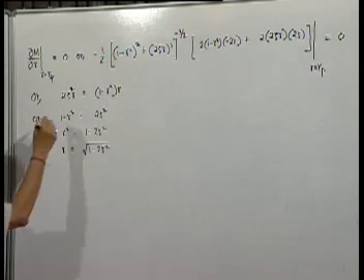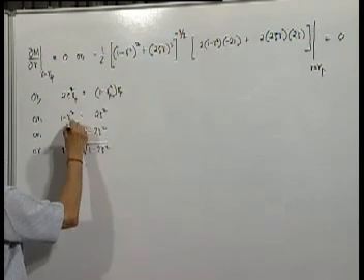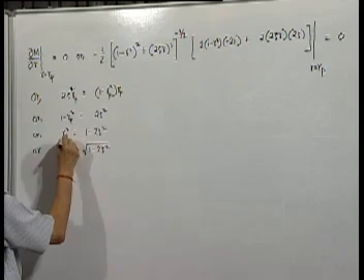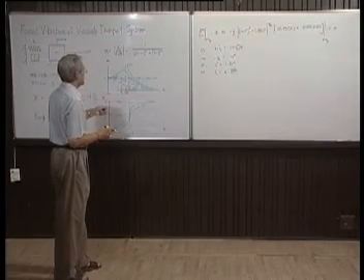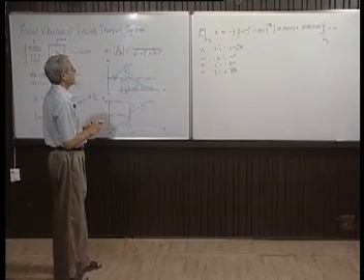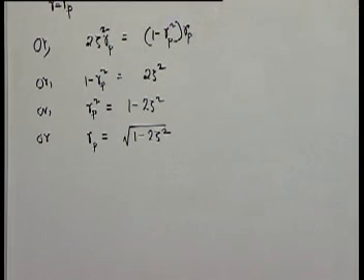I must here put r equal to r_p. So, the value of the frequency ratio where the magnification factor reaches maximum is given by this. When zeta is equal to 0, that is the undamped case, obviously r_p is equal to 1.